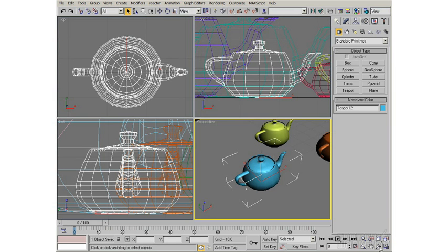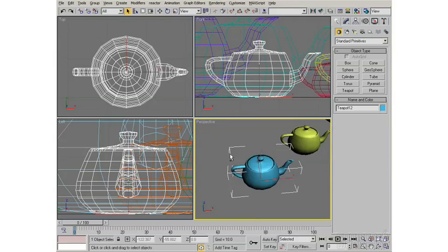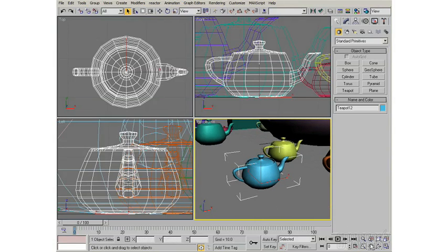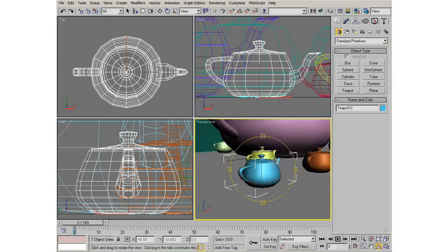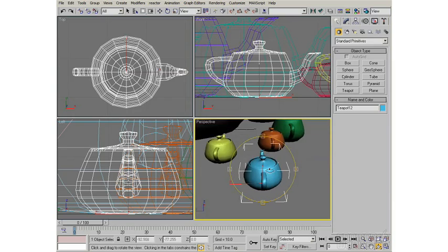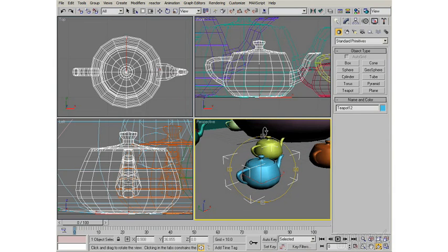Next to that, you have this Arc Rotate. Remember, we talked about Arc Rotate when we hold down Alt and the middle mouse button. That's a quick shortcut for arc rotating. And so you can invoke the tool, and what you get is a little manipulator here. You can click anywhere on the inside of it and rotate around. If you pick on these little top and side boxes, it'll allow you to constrain your rotation to one direction or another.